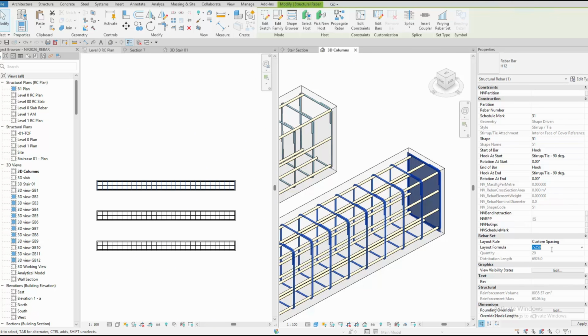So as an example, I might want to set 25% of my beam to have a spacing in here of 100. I'll separate that with a semicolon. Then I might want 50% of the beam, which would be the part in the middle, actually separate it here with 300 centres, and then we'll go back into the 25% at 100 spacing.